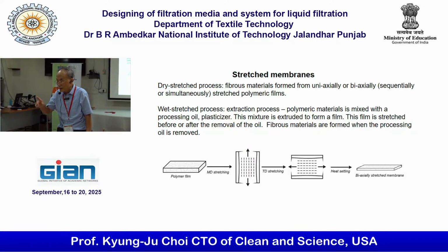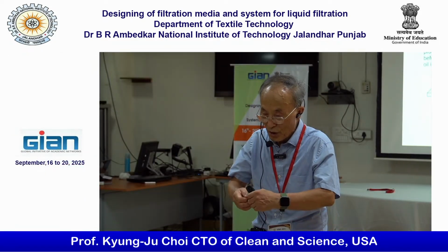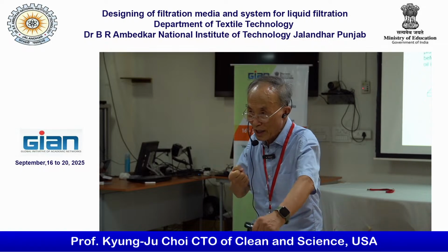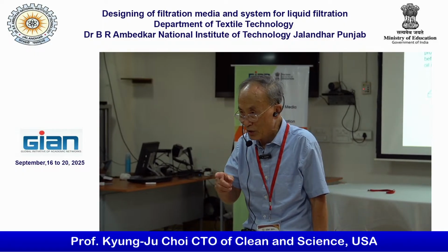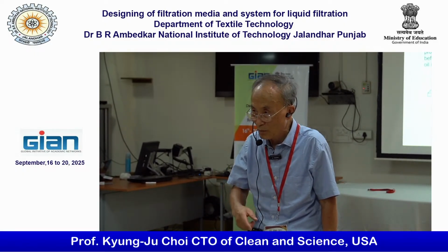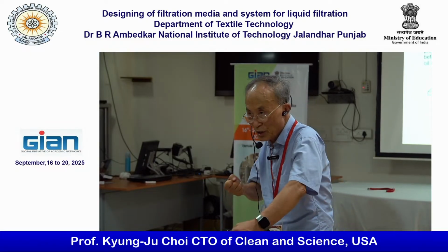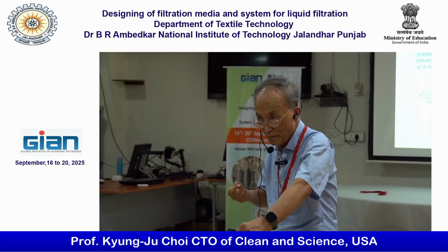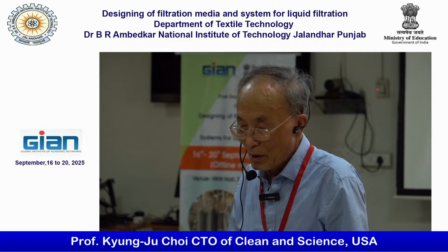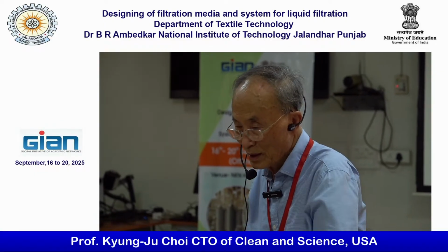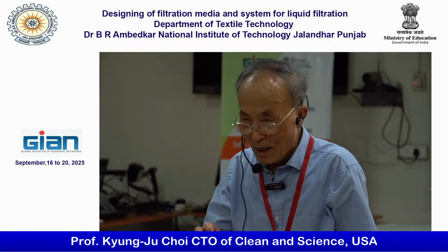The other important thing is, first you have to stretch in the machine direction only. We call it MDO, machine direction oriented. Normally, when you stretch in the machine direction, you have to apply heat.